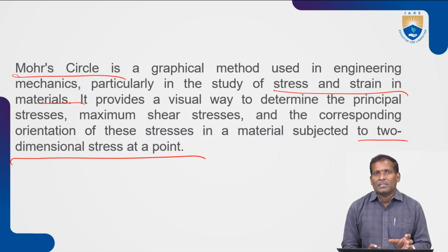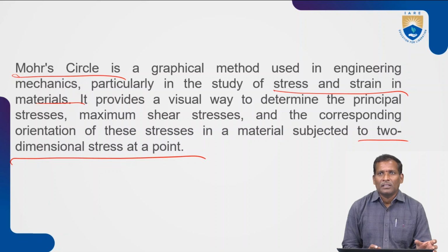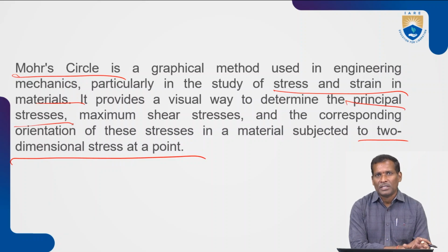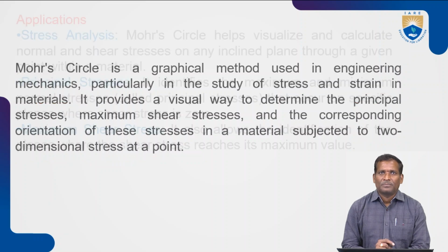By seeing this Mohr circle, you can find the maximum and minimum principal stresses, the maximum shear stress, and the corresponding orientation of the stresses.